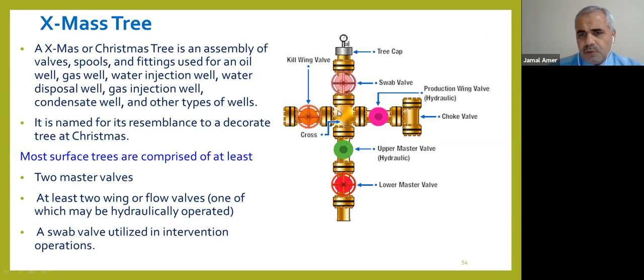Composite, with this kind of Christmas tree, we call it composite because we see flanges here. Flanges connect each valve to the Christmas tree. While if it's block solid, we don't have these flanges. We have metal, one piece of metal only. We don't have many flanges because flanges with gasket are a potential source of leak.